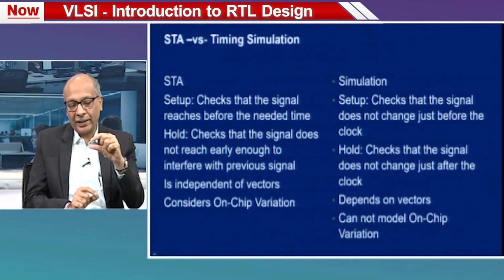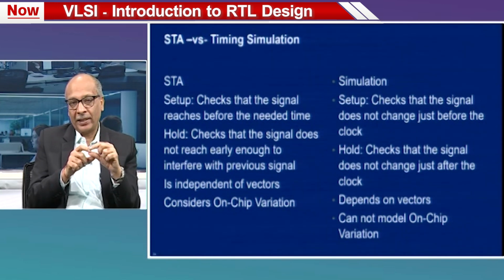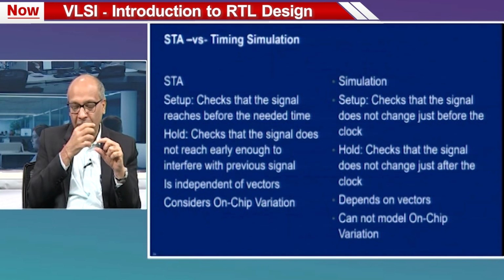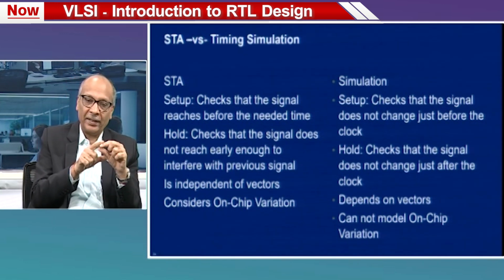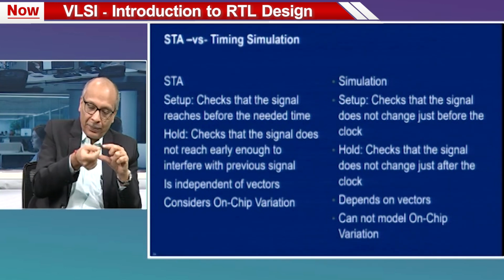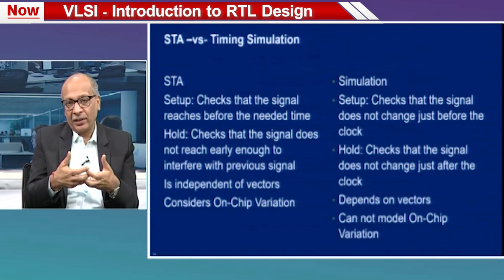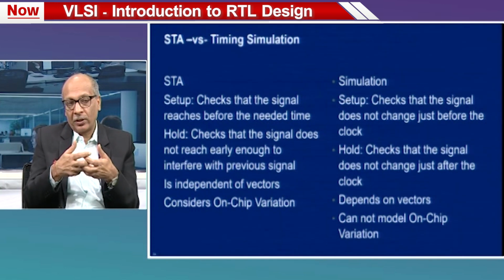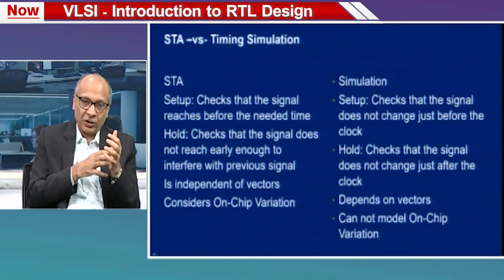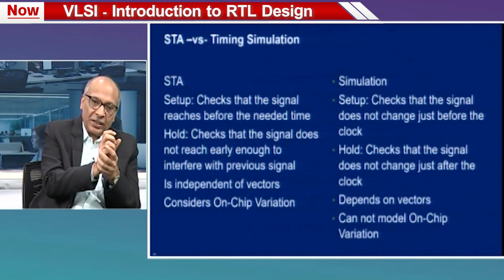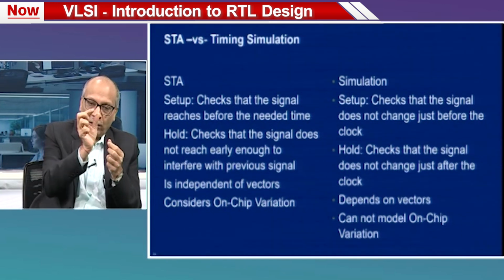You should think of an AND gate. The delay for an AND gate is dependent on many factors, but at least some of those factors are the voltage of that AND gate, the temperature of that AND gate. And when we were manufacturing, the quality of that transistor, whether it was a strong transistor or a weak transistor, all these things affect the delay of that AND gate.